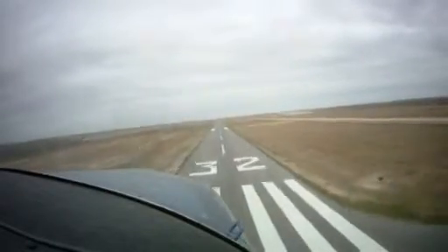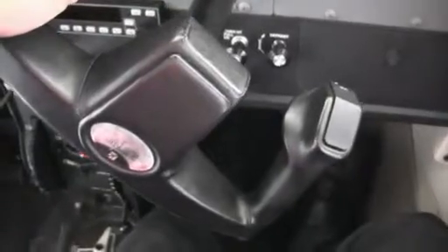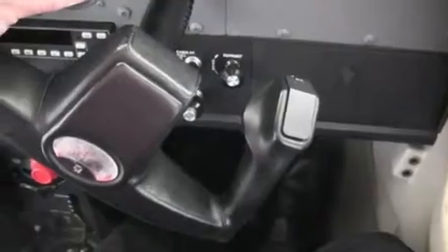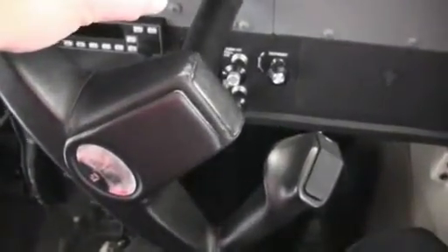In this video, we are going to perform the sideslip method since the wind conditions prevailing were very strong and crossing. To use the sideslip method, the pilot aligns the airplane nose with the center line of the runway, notes the rate and direction of drift, and then promptly applies drift corrections by lowering the upwind wing. The airplane will have the tendency to turn in that direction, so it will be necessary to apply sufficient opposite rudder pressure to prevent the turn and keep the airplane nose aligned with the center line. In this technique, the drift is controlled with the ailerons and the center of the runway with the rudder.